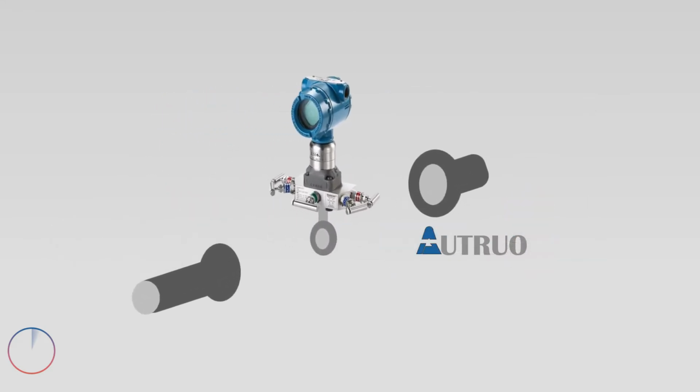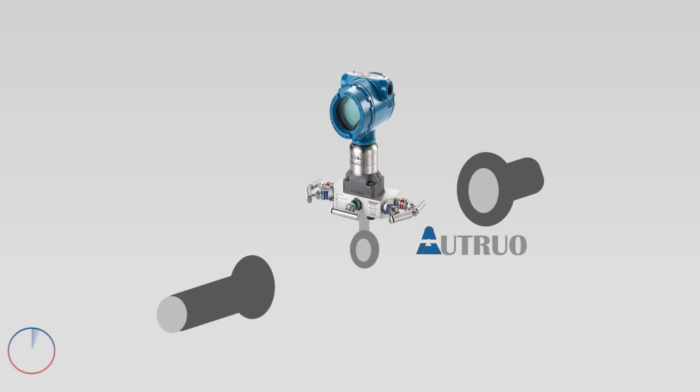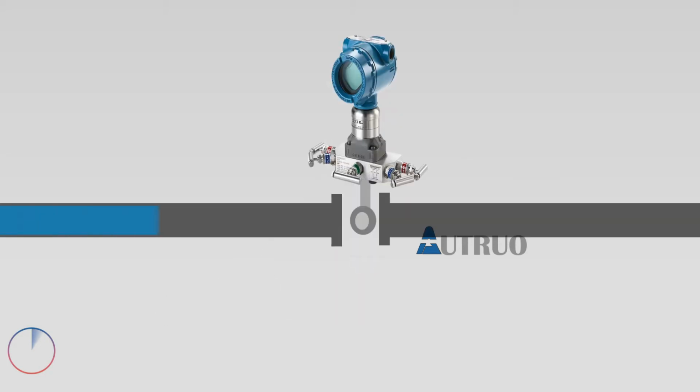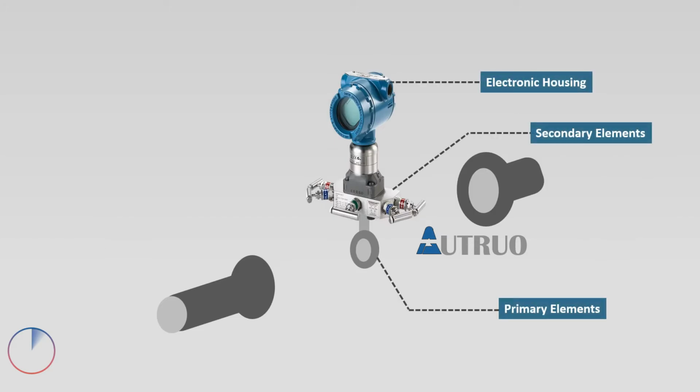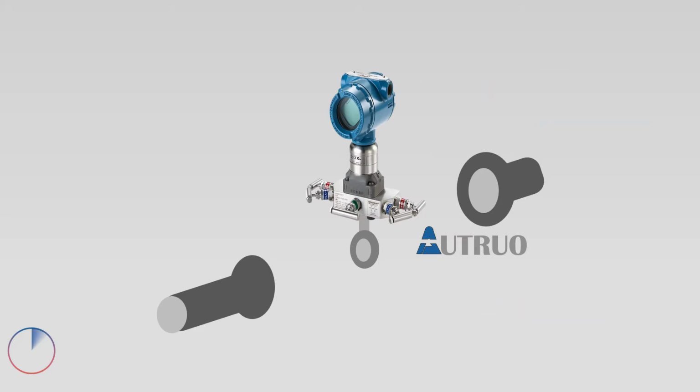Let's begin with the differential pressure transmitter with respect to flow. Differential pressure transmitters, delta P or dP as it is known in industries, were primarily designed to measure pressure, that is, before and after the fluid encounters an interruption. This interruption could be a filter or pump. The delta P comprises primary elements, secondary elements, electronic housing, and process flanges. The electronic housing features an amplifier board and wiring terminals.